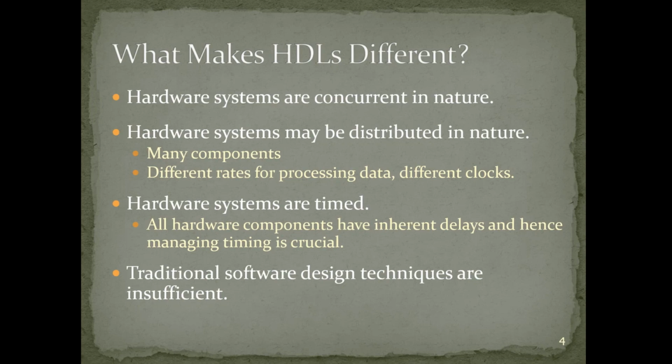Also, hardware systems are timed. What I mean by that is that any more complex design would basically run based on a synchronizing clock. So everything is clocked, it's timed. Things happen at very well-defined periods of time as the clock dictates. Sometimes we can have multiple clocks, but generally devices tend to be synchronous in nature, so there is a synchronizing clock there to make sure everything works properly.